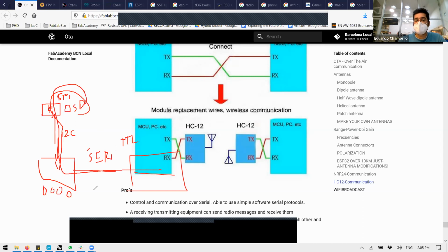How can these guys check that the communication is properly done? It's serial, it's a quite basic connection. They use echoes. So for example, if you are sending a G-code, it usually has lines of code, no? This guy sends line 1, and this guy answers line 1 read.